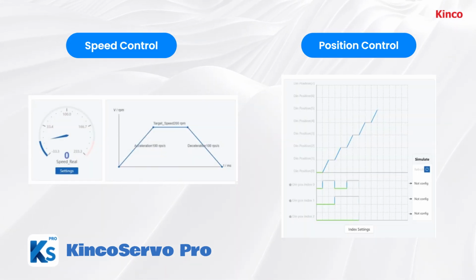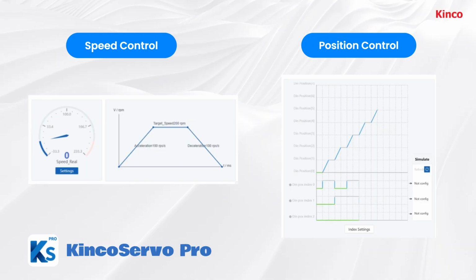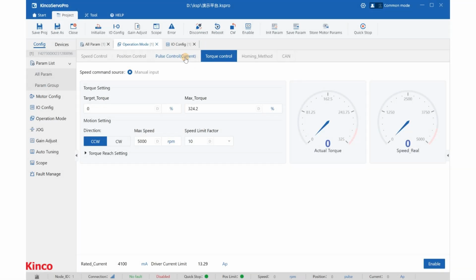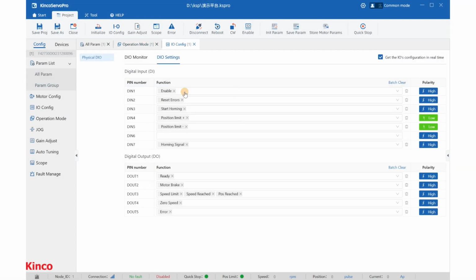In the previous episodes, we introduced speed mode and position mode, two of the three basic control modes of servo drives. Today, we will explore torque control mode in the Kinco ServoPro. First, after connecting the servo, check the I/O configuration.